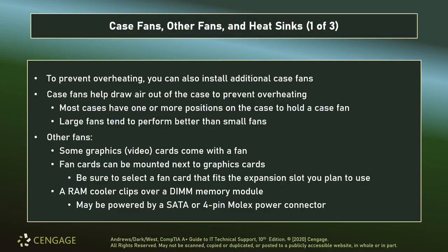If we need to enhance the graphics card's ability to exude its own heat, we can sometimes use what's called a fan card, and these will often be mounted next to a device in order to provide additional airflow. Now, make sure that you're providing a fan card that fits the expansion slot you plan to use and that it doesn't impede anything else that's connected inside of your device. More often than not, fan cards are considered a legacy product now, because if you're going to use a graphics card, hopefully the cooling that it provides on its own is good, and that if you need anything further, you can add case fans or move to liquid cooling, which is definitely a much more aggressive method.